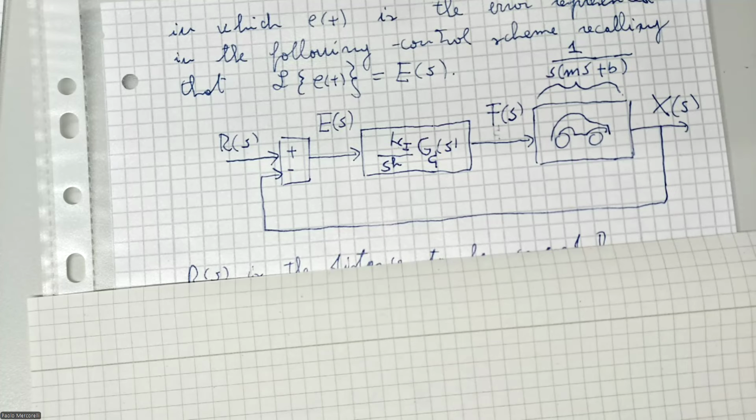If you think about the capacitor we have seen last time, if the change generates a step in the voltage of the capacitor, the current is an impulse. We have to know if it's an impulse or not, because an impulse theoretically could generate problems in the system. Impulse mathematically is an infinite amplitude. This is just a mathematical expression, but you remember I tried in the first lecture to show you what practically an impulse is. It could also destroy the system, no? Because in a small time, large, not infinite, but large amplitude.